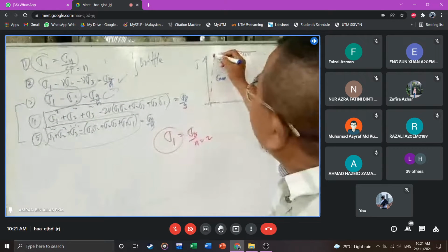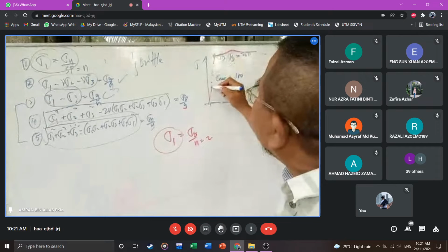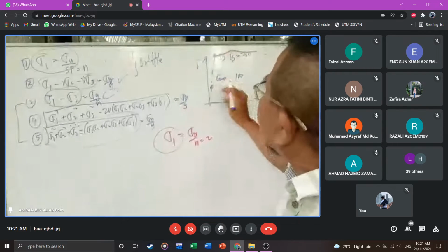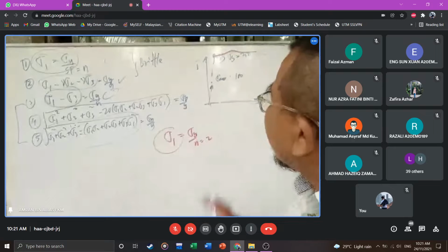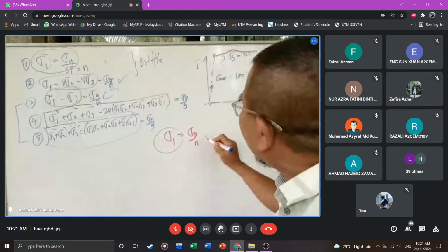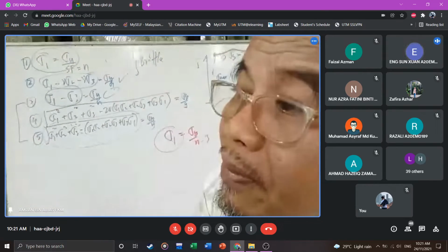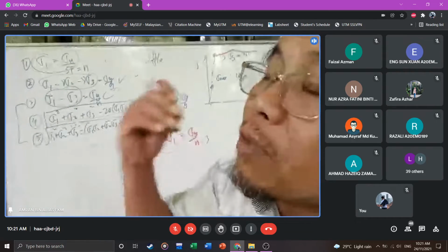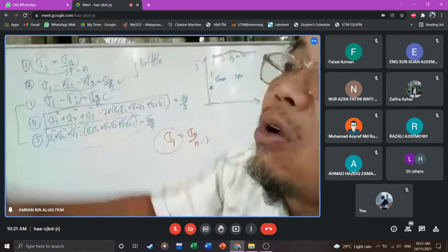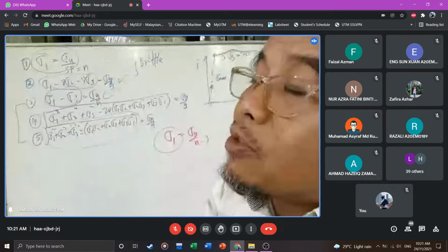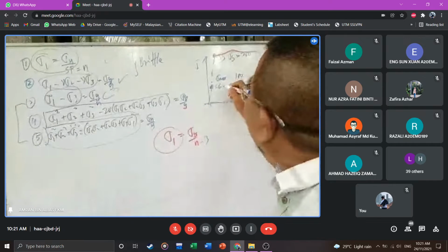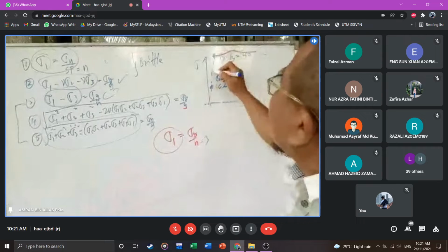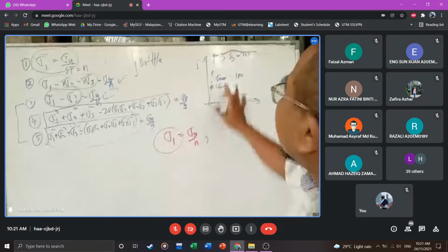What if safety factor of 3? Here we set the maximum. Now safety factor of 3. What is the meaning? 1/3 of sigma y. When we have the maximum stress, 3 times more. Let's say this value is 66.6, times 3 becomes 200.